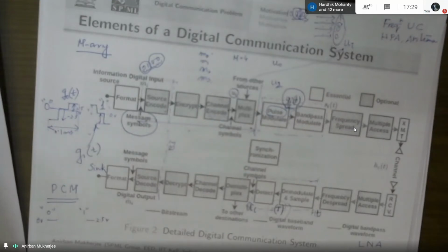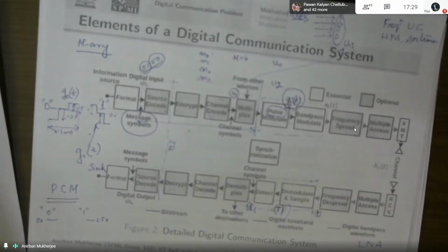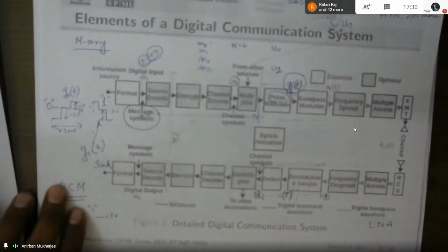When you are generating these pulses, the pulse modulation block allows for a variety of binary and M-ary pulse waveforms that we have studied. We'll discuss the usual attributes of these waveforms, and the filtering, because inside this pulse modulation there's a filtering block that I have not written here. We need these filters because we have certain bandwidth requirements, and due to filtering the pulse occupies more than just one bit time. Just to try to understand, here it's crucial information.